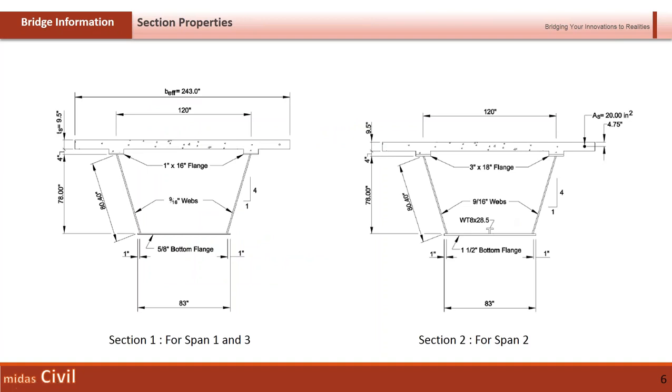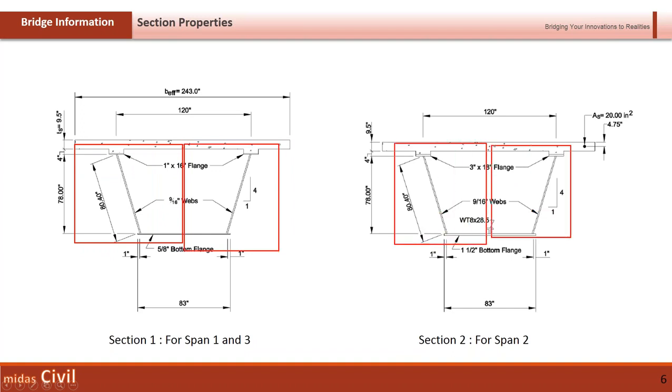So these are the section properties that we'll be considering in our model. As you are already aware, if you are going to do a steel tub bridge, usually you will consider this I section separately, and all these things separately. It leads to some design issues if you model in such a way, because it doesn't take the shear and torsion properly.